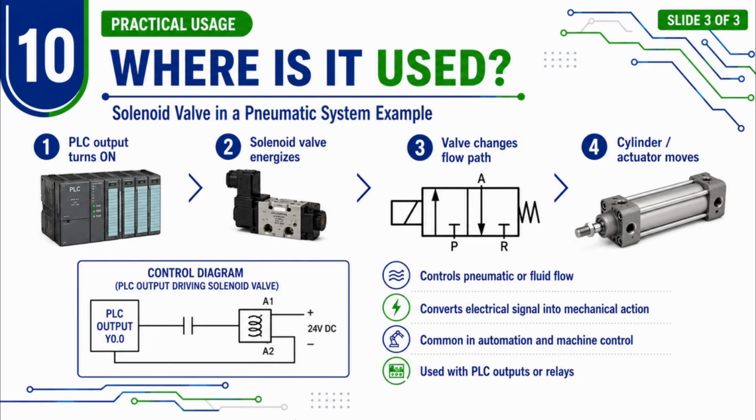If it is a 3/2 valve, it is often used for simpler control applications. If it is a 5/2 valve, it is very common for double-acting cylinder control, where the actuator must move forward and backward.